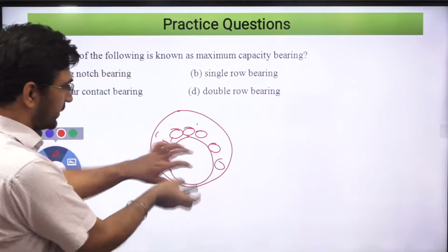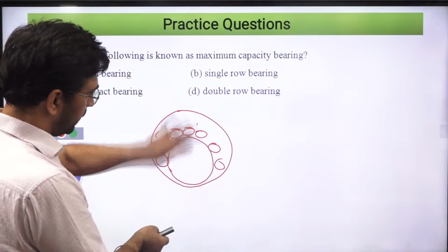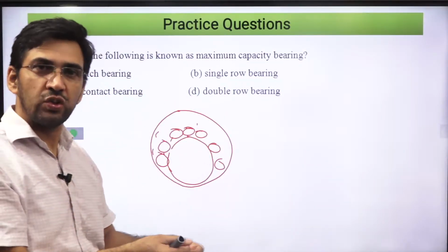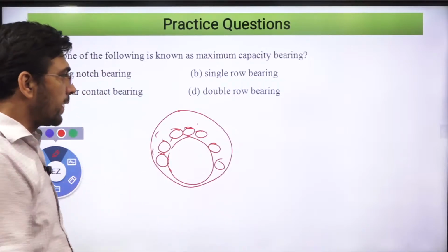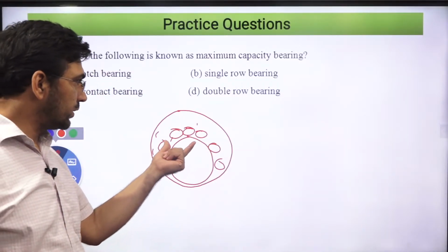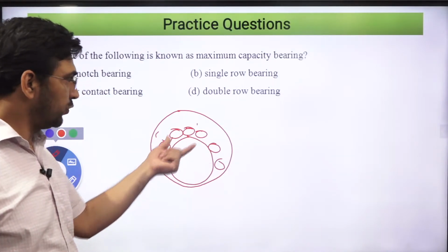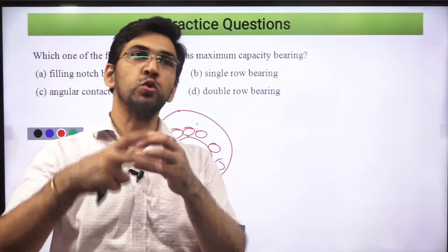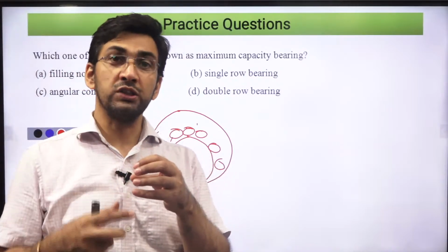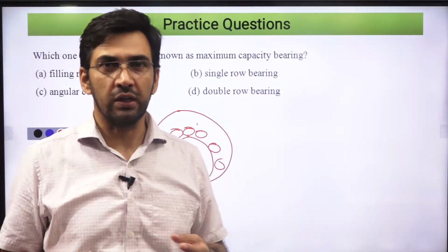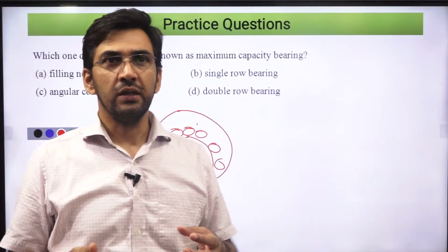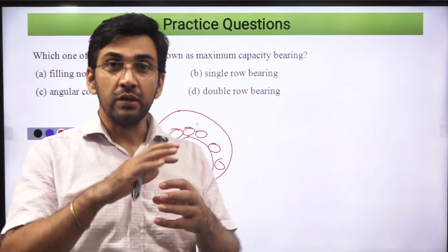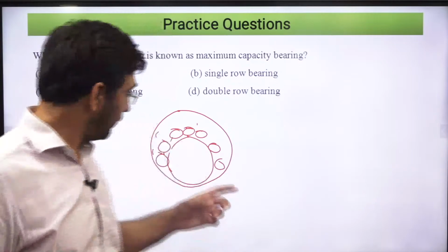and then you adjust these rings. You pull it a little up and then adjust, and then equally space, use the cage and all that. That is how you normally do. But because of this, if you use this method of putting the number of balls between those two races, then the number of balls that can be accommodated are not large. They are limited. Right? So they are limited. The number of balls that you can introduce are limited when you follow this approach.